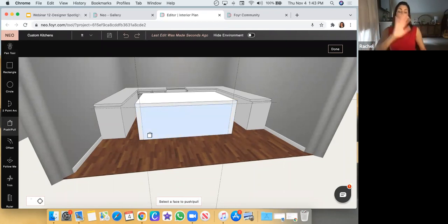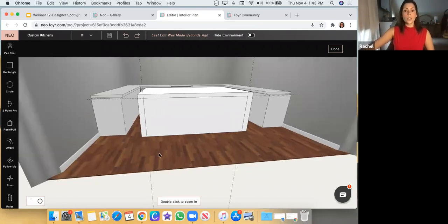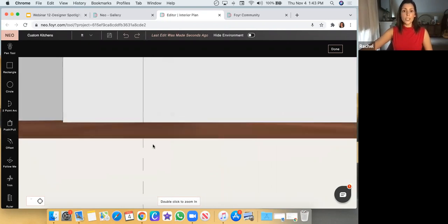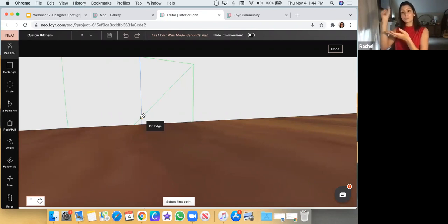And now that I've defined it, and again, I'm just clicking the escape key, you'll see these are two separate planes. If ever you hover your push-pull cursor over a plane that you've just defined with a rectangle or pen tool, and the whole thing highlights, don't push-pull, because that's telling you that at one of these edges, that pen has not been joined. So you can just zoom into the edge here, and you might find that there's a little gap, and then you can just grab your pen tool. It'll automatically snap onto the edge for you, click, and then you're just closing off that gap.